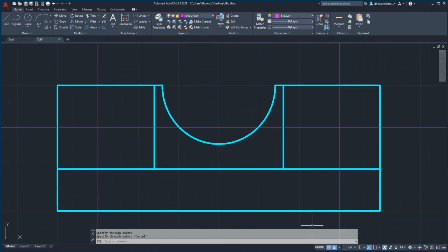So those are the center lines for my holes. And I think I'll do the one right here too, just to point out that that is the center line of this larger arc, because that I want on this whole construction layer. Okay.